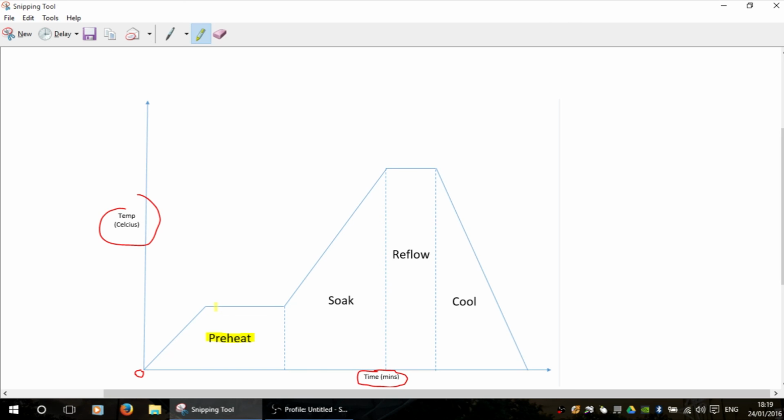And copper is very, very good at absorbing and drawing heat away from where we're going to be reworking. So we're putting heat into the board, and the board itself is trying to absorb that heat out of where we're putting it. So what we need to do is we need to absorb as much heat as possible safely into the board so that it saturates the board. And it can't draw heat away, but instead it ends up building up in the area that we're interested in.